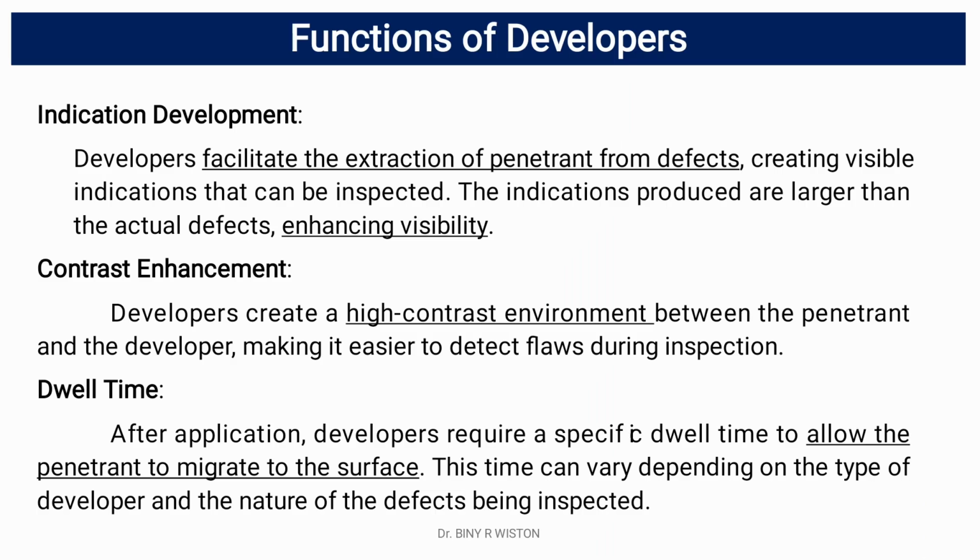Functions of developers. The main functions of a good developer include indication development, contrast enhancement, and dwell time. Developers facilitate the extraction of penetrant from defects, creating visible indications that can be inspected. The indications produced are larger than the actual defects, enhancing visibility.